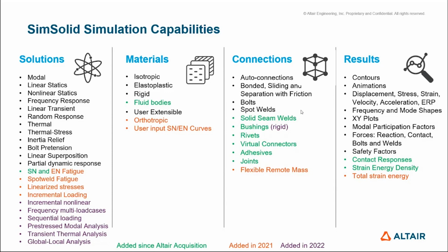Results: contour plots, animations, your typical displacement, stresses and strains, frequency, modal shapes, modal participation factors, critical in your dynamic assessments in terms of how much of a percentage of the mass is acting for a particular frequency, safety factors, contact forces, and total strain energy.